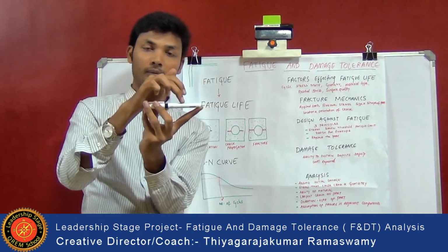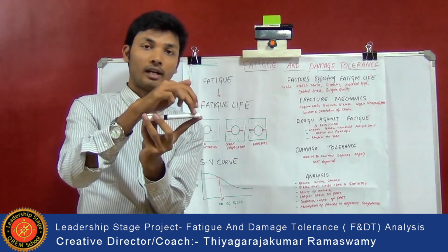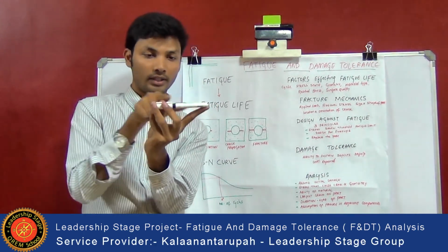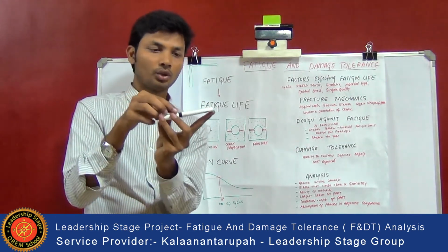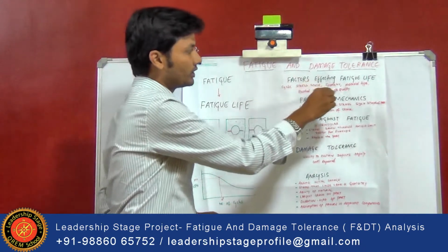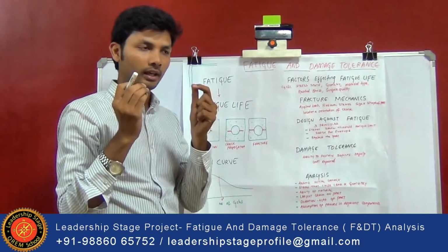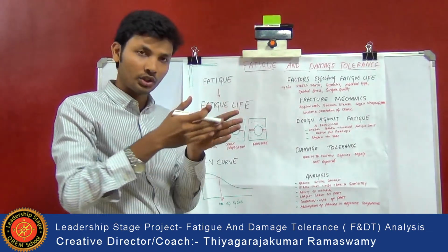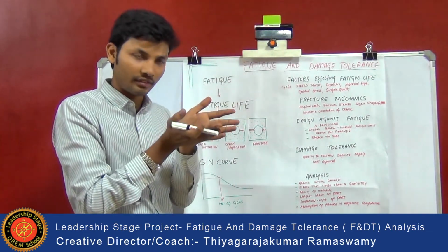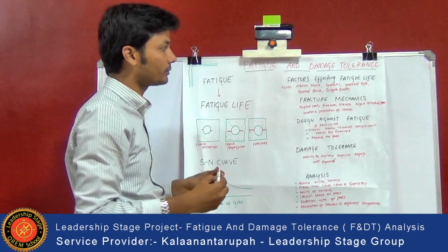Definitely there will be a crack in between somewhere over here, but the fatigue life will be much higher because the design of the geometry of this component is totally different to the earlier one. So even the geometry plays a crucial role over here. For a complicated component, you will have weak links, or a complex geometry or complex connections of the surfaces, which will also lead to cracks.